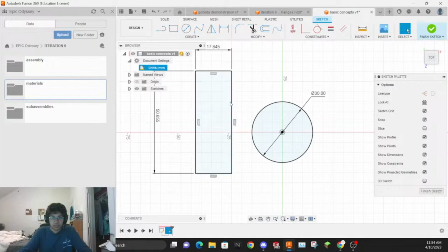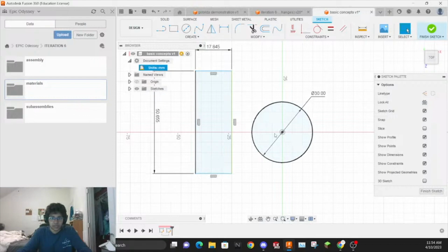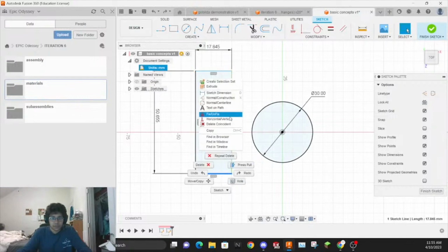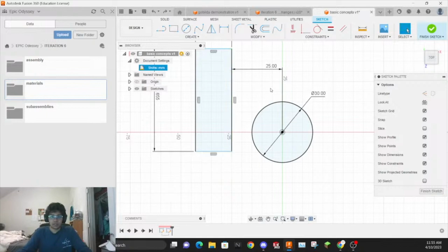So now this shape will fix itself on this plane. Here, let me show you. It should not move now. Yeah, you see, I can't even select it to move. Now it's fixed to its position on the right and left side. And now if I want to fix this point too, now I can't even move the rectangle whatsoever. So if you want to keep things in the position they are, you don't necessarily have to constrain. You can just fix two sides and bam, you're good, right?